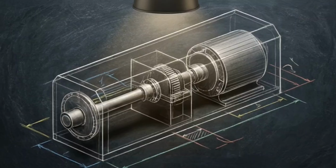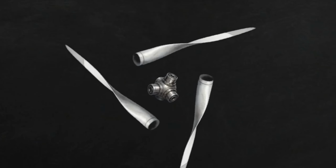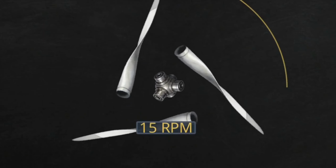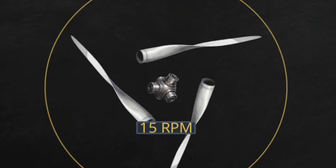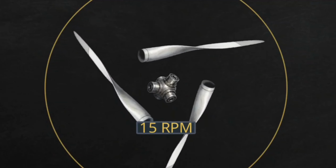This X-ray rendering takes us inside the nacelle casing at the top of the tower to track that newly generated torque. Inside, there is a severe mechanical mismatch between the aerodynamic rotor in the front and the electrical generator in the rear. The rotor is constrained by size. It must turn at a very slow RPM to prevent the massive sweeping blade tips from breaking the speed of sound. The generator is constrained by frequency.